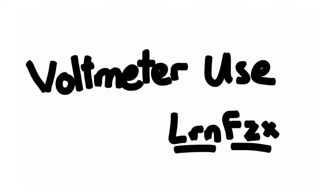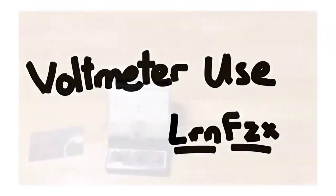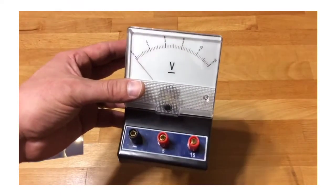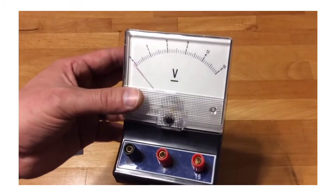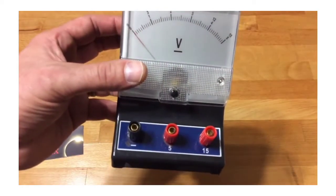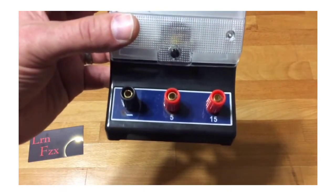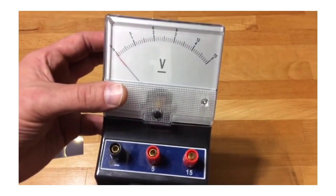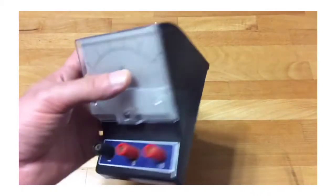Here is how to use a voltmeter. The instructions work for any meter, but this is the one that we use here in class. The big fat V says voltmeter. Notice that there are two ranges, the upper range to 15, the lower range to 5, and the connector is down at the bottom. The black one is negative, and there are two positives, one for the 5 volt range at the bottom, one for the 15 volt range.